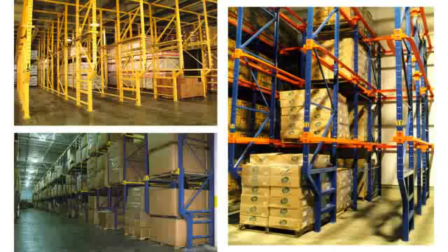This next slide shows drive-in racks. Drive-in racks are a very good form of high-density storage racks. Their only one drawback really is that the only pallet position that is really available for picking at any one time is the very front position on any level. But they can be serviced from the same aisle. Normally, one of the other drawbacks is that the first pallet in happens to be the last one out in